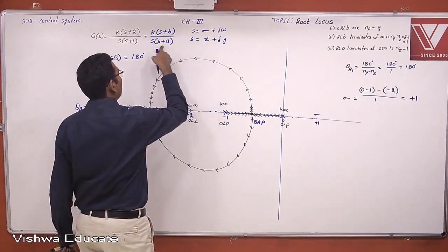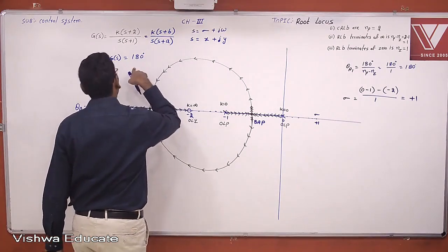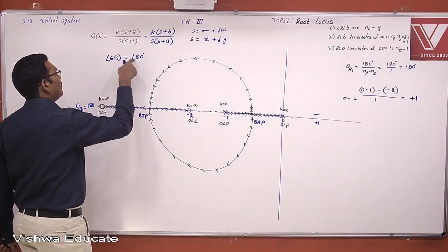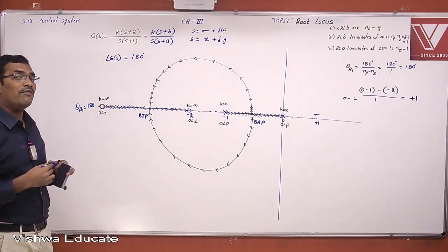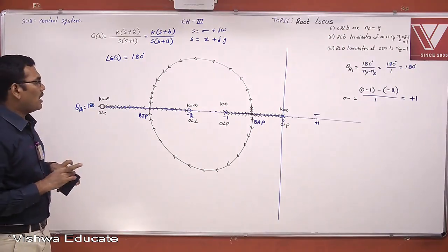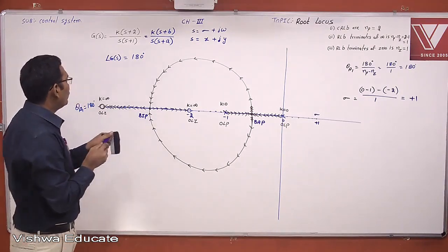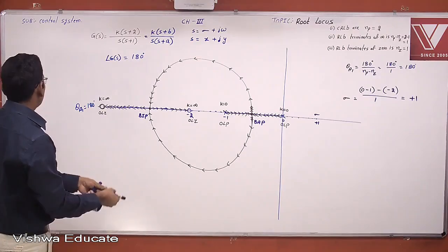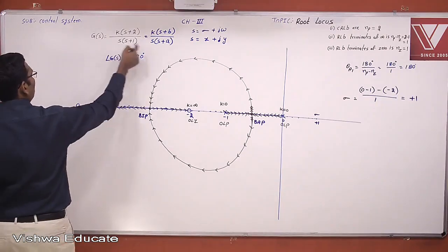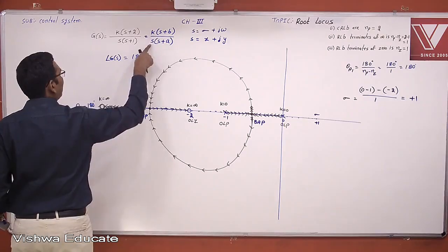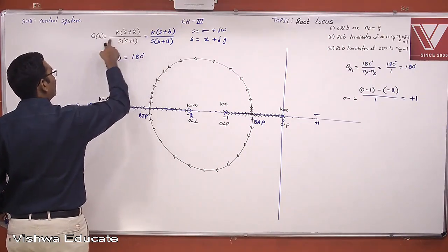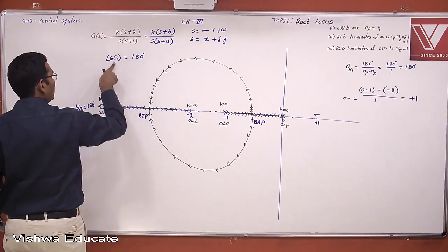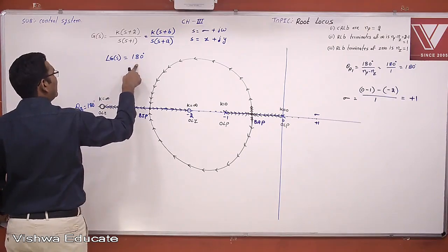Substitute this and find the angle of the open loop transfer function, equate that angle to 180 degrees and simplify that equation, and you will form a circle equation. After replacing, we have x plus jy plus b over x plus jy into x plus jy plus a; measure the angles of the open loop transfer function and equate to 180 degrees.